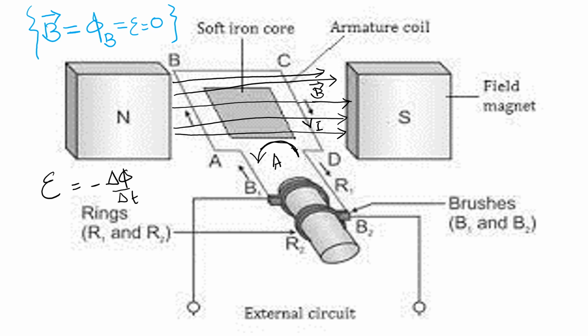In the downward direction, this electric current will move and reach the slip ring. And whenever it reaches a slip ring, it will then go to an external circuit through the carbon brushes. After passing through the external circuit, it will again go through a carbon brush and reach the AC generator.